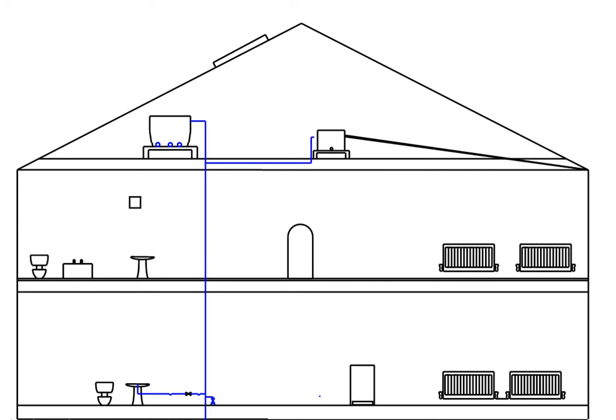We bring our supply of water then over to our expansion vessel. This is used here for our expansion pipe coming up here from our primary circuit, which is up from our boiler up to our cylinder. We have our cold supply of water come down here to our toilet and also to our sink, bath and our toilet down in our bathroom. There you can see we have a valve to turn it off in case you want to fix up taps or fix the toilet or whatever.